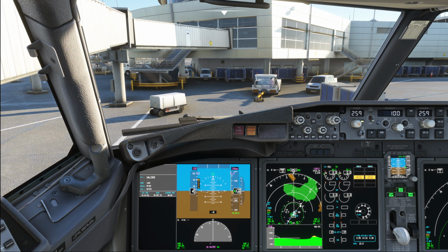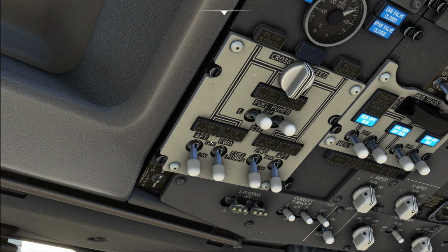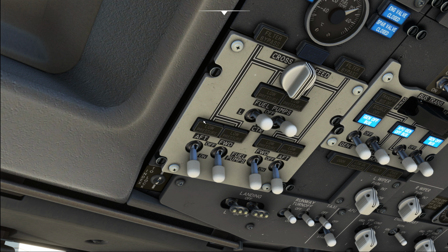Doing this is rather easy. You take, let's say for example, the entire low pressure switch over here, you pull it out, and then you can simply take the bulb out, put the new one in, and stick it back into the panel. Be very sure that the switch actually sticks right back in, especially on the overhead panel, and that it holds.